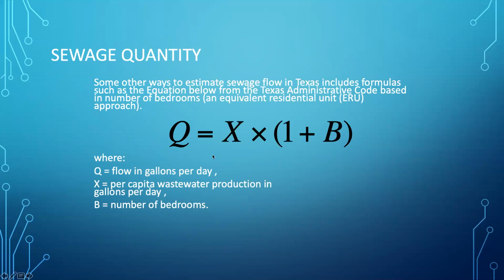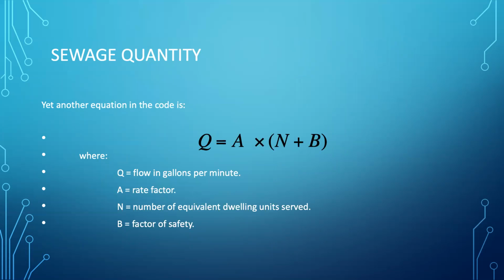So this one would be appropriate for Somewhere USA, for instance, because that's a small enough study area that we've been using throughout the semester to practice some of these procedures. Pretty much 4 bedrooms per house in the Somewhere USA thing, and then multiply by the number of connections. That would give you a pretty effective way to estimate wastewater discharge in gallons per day from that entire subdivision.